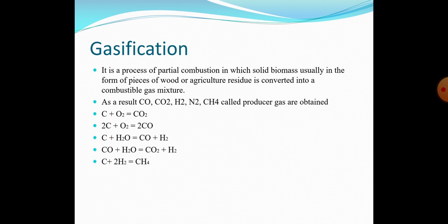In a typical combustion process, generally oxygen is surplus, but in the gasification process, the fuel is surplus. Why? Because the combustion products require partial combustion. So, for partial combustion, the products pass through the glowing layer of charcoal for the reduction process to occur. During this stage, both carbon dioxide and water vapor oxidize the char to form CO, H2, and CH4.